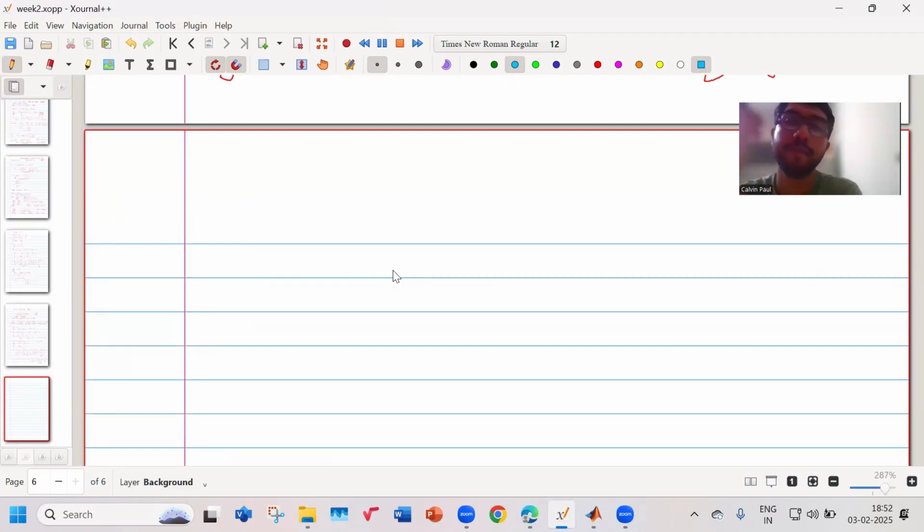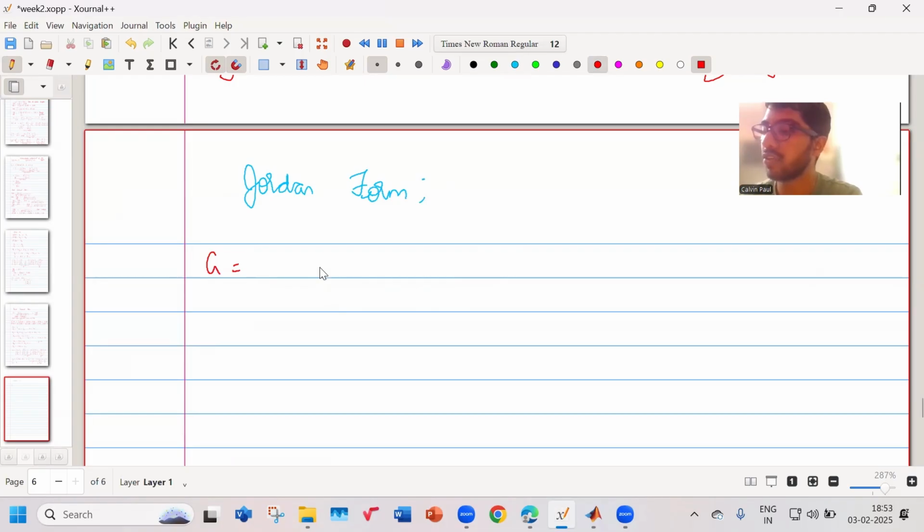So okay, now we have done two state space representations of the system. Now let us consider the third form, which is known as the Jordan form. So in this case, let us consider transfer function g, which is given by 1 upon s plus 3 into s plus 4. Okay, let us consider this system.